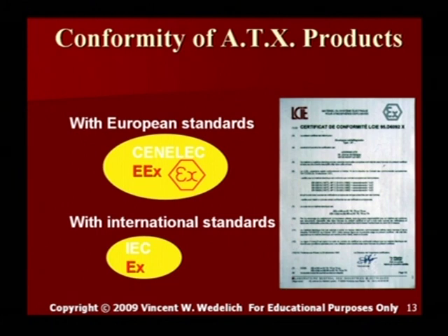If the area is a Zone 1 or Zone 0 classified area, you cannot self-certify this area. You must use an authorized notified body to install that equipment, such as TUV, BASEEFA, places like that, or companies like that.